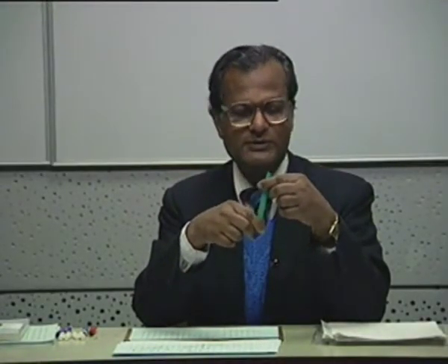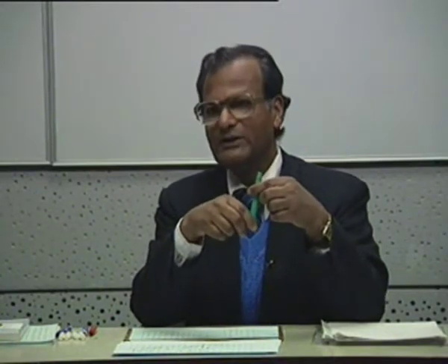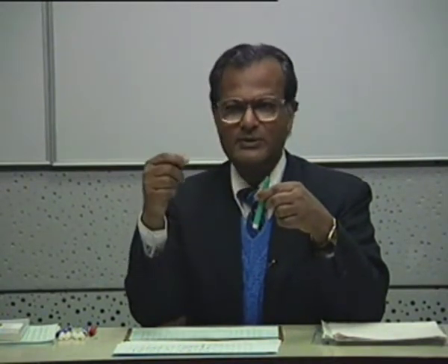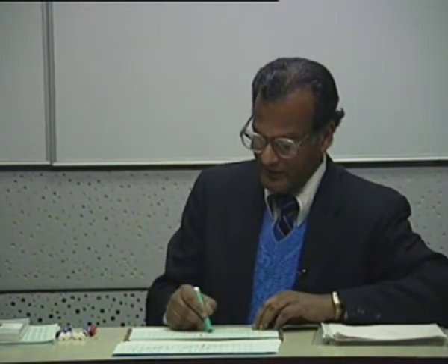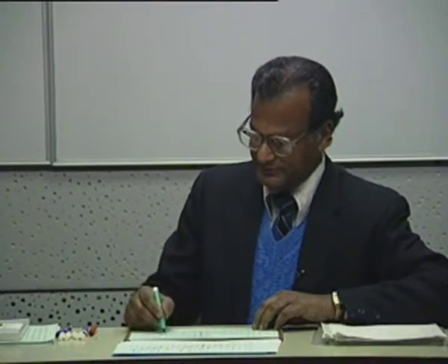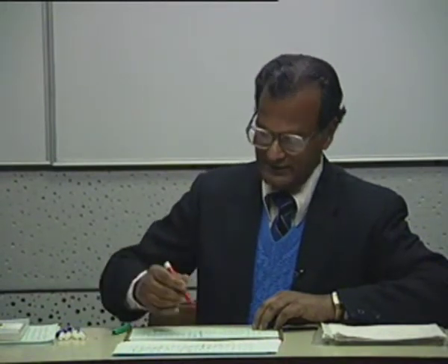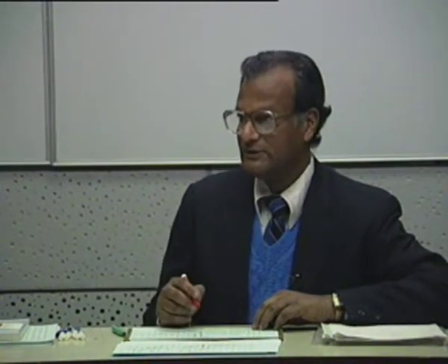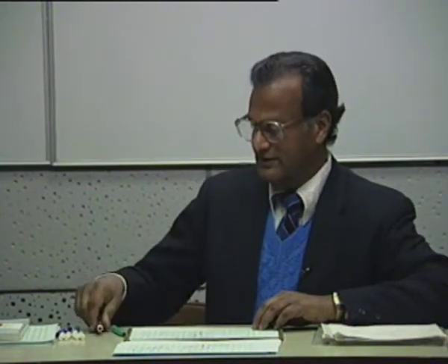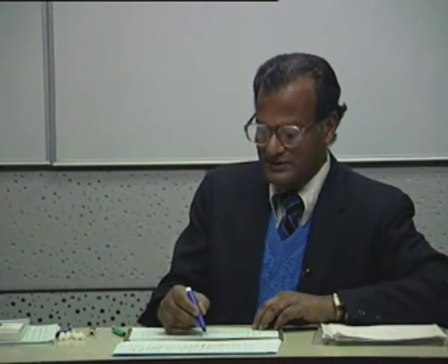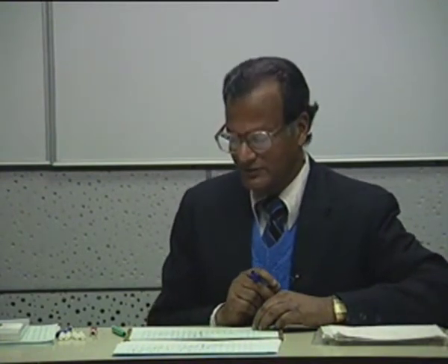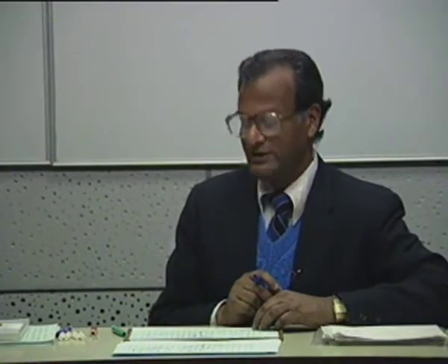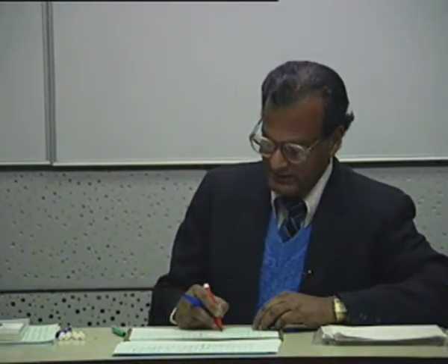If this core is non-magnetic, for example a piece of pencil or a piece of wood, then the flux current relationship phi versus I is fairly linear. Okay. On the other hand, if this core consists of iron, which is a magnetic material, then as you know, iron, the amount of flux with increasing current tends to get saturated.